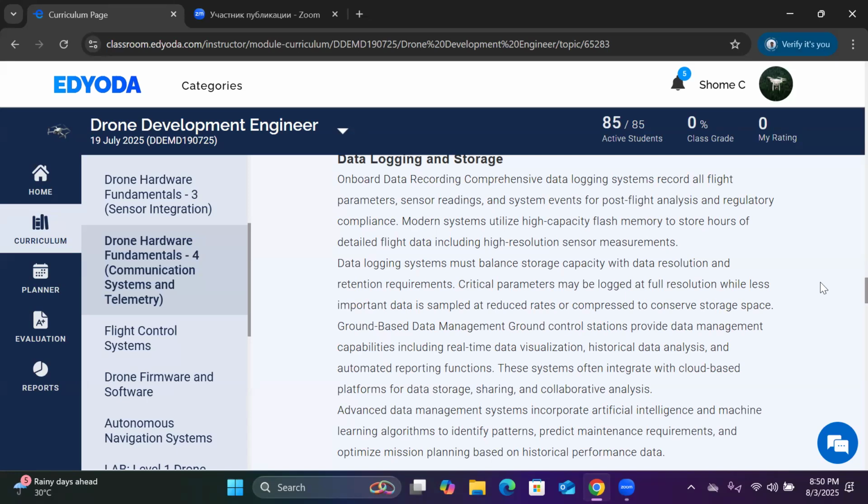Suppose your constellation is supporting 12 to 14 satellites, and your GPS receiver is able to latch with 6 to 8 satellites. Based on those 6 to 8 satellites, by triangulation, you are getting the lat long parameter. These lat long parameters, either with the DGPS, the GPS, or the real-time kinematics, are required. So those data need to be streamlined by real-time data streaming to your ground control station.